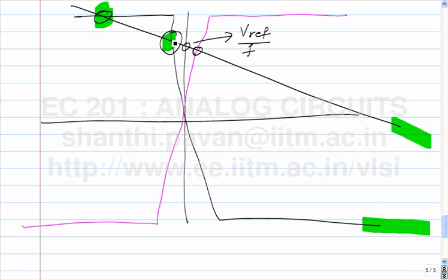Okay? So if there is a small perturbation, since what comes back once you go through the loop is much larger than the disturbance, it will be plus AF times the disturbance, and it is in the same direction, so it will push it even higher and higher and higher, and eventually until it either reaches this operating point or the other operating point beyond the board.